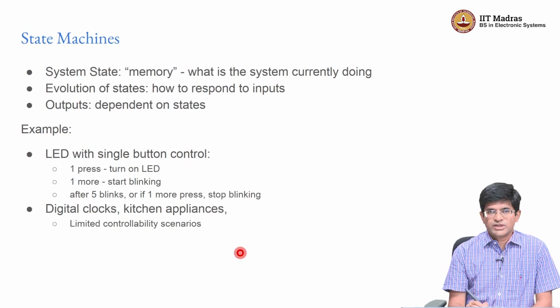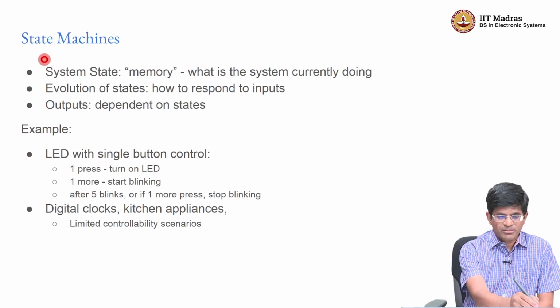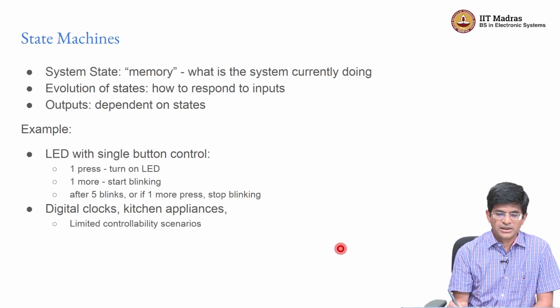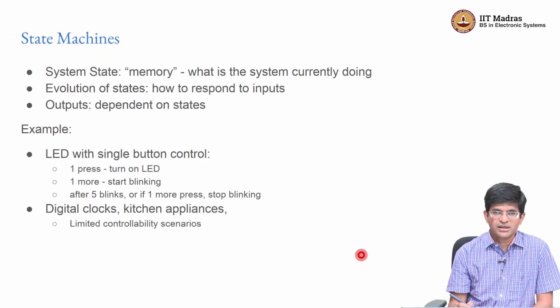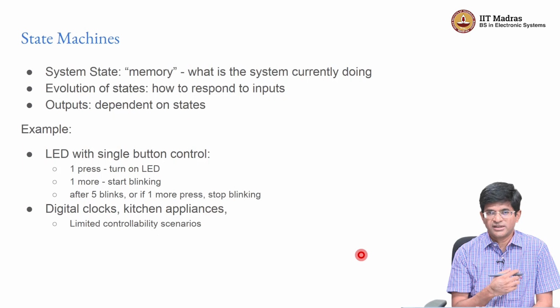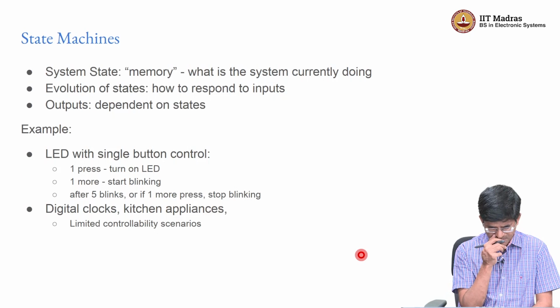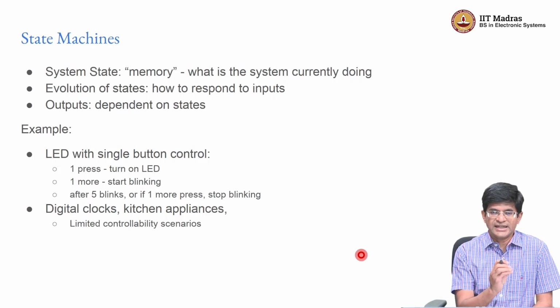One of the first and foremost patterns corresponds to the concept of something called a state machine, right? Now, from the course on digital systems, you have already heard of the idea of a finite state machine, right? Essentially what it says is there is some kind of set of registers which hold certain values, and what the finite state machine does is it looks at the present state of those registers, it looks at the inputs that you have, performs some computation, usually using combinational logic, and then updates the state, while at the same time also generating certain outputs. Now, that's purely at the circuit level, right?